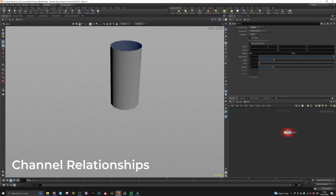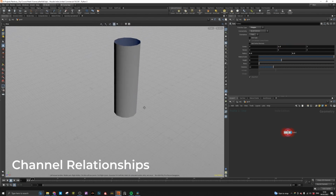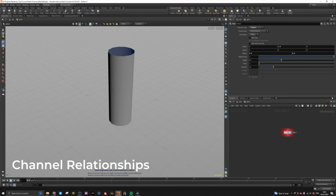Now we can see, again, if I change this to 3, this needs to be 1.5 to set the base on the ground plane. This means the relationship between the height and the center Y position is 1/2. So whatever the height is, if we set this to 1/2, the base will always be set to the ground. So in that case, we can reference this here to this height. This is also known as channel referencing.